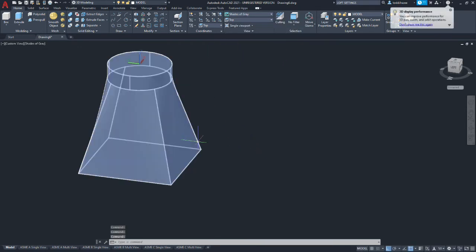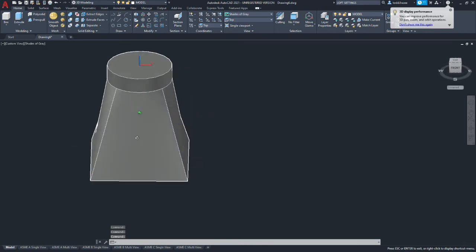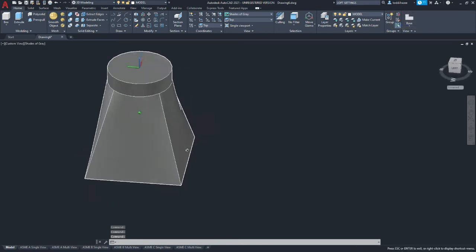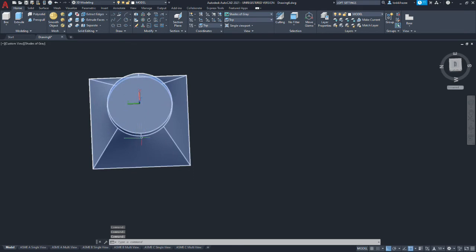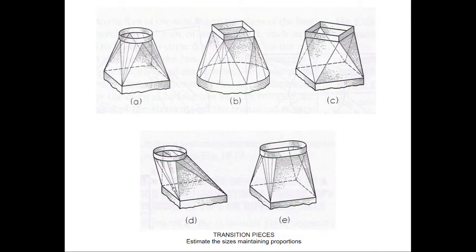And this is close. It's curved here, but we don't have a true flat here. If we are to look at our drawing, we pretty much have a triangular flat that terminates with radiuses on the corners. We're not going to be able to achieve that by doing a three station loft.